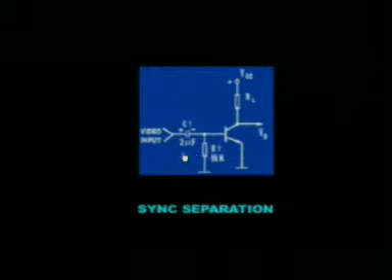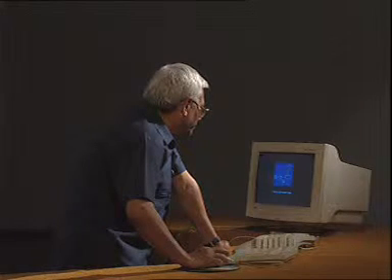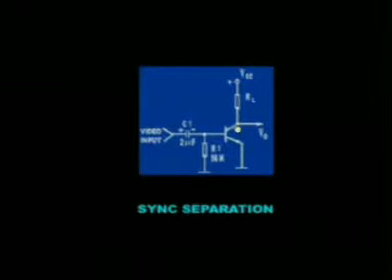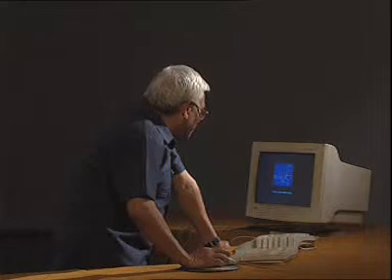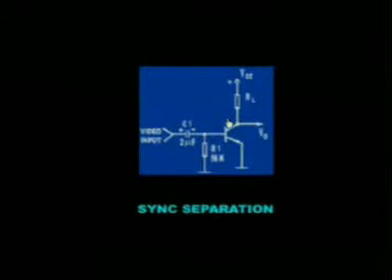Let us see the process, how these sync pulses are separated. Here the same capacitor C1, which is of 2 microfarad, and the resistance which is of 56 kilo ohm, have given the biasing as a self bias to this transistor, and the collector of this transistor is biased through the supply. It is an active device. Transistor is an active device. It means it has the capability to delay the signal.